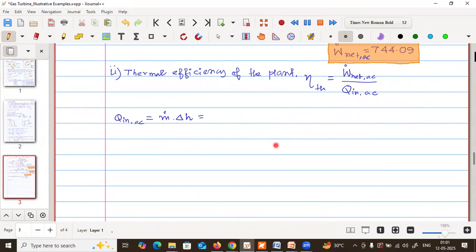Delta H, because for these steady flow processes the energy, that is heat input, is equal to change in enthalpy. Other quantities are nullified in the first law, so the enthalpy remains. So always you will refer to the first law for the steady flow devices for these equations.